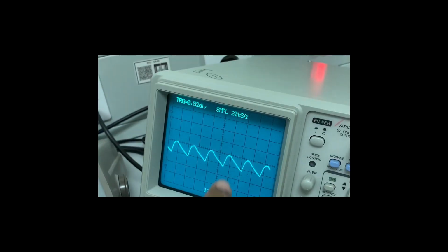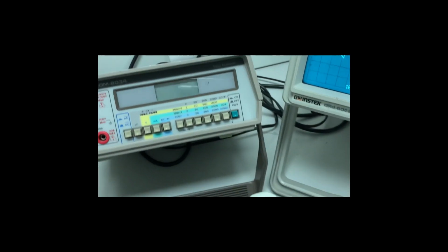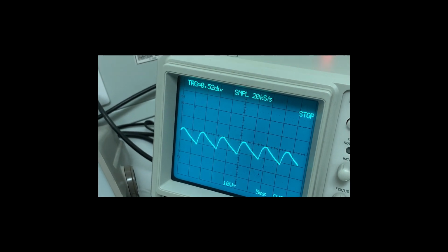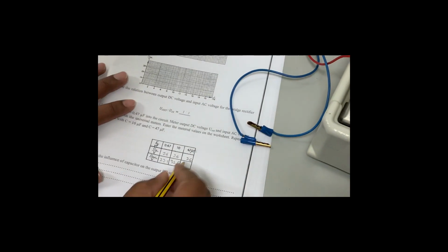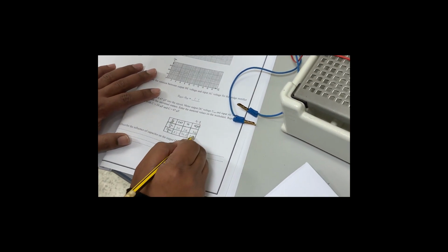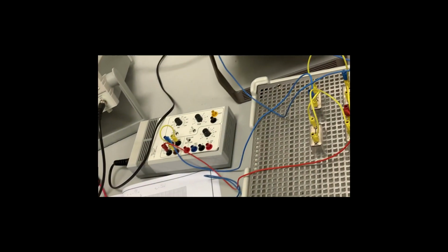So just check, it is not with the 10 micro you are getting approximately DC, okay? Because 10 micro is a lesser value, so 4.7 is greater. 4.7 micro, make the correction, it is 4.7 and it is 30.6, okay? This is the bridge rectifier of full wave rectifier.